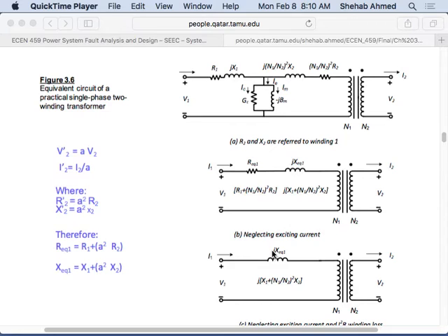So you will have to typically design your transformer such that you minimize the value of the resistance considerably. So in power systems, especially on the transmission side. Distribution side, we are sometimes, again, crammed on space. We don't have space in the building. So the distribution transformers may be smaller. Smaller transformers mean smaller wire, mean higher resistance, mean higher losses, right?